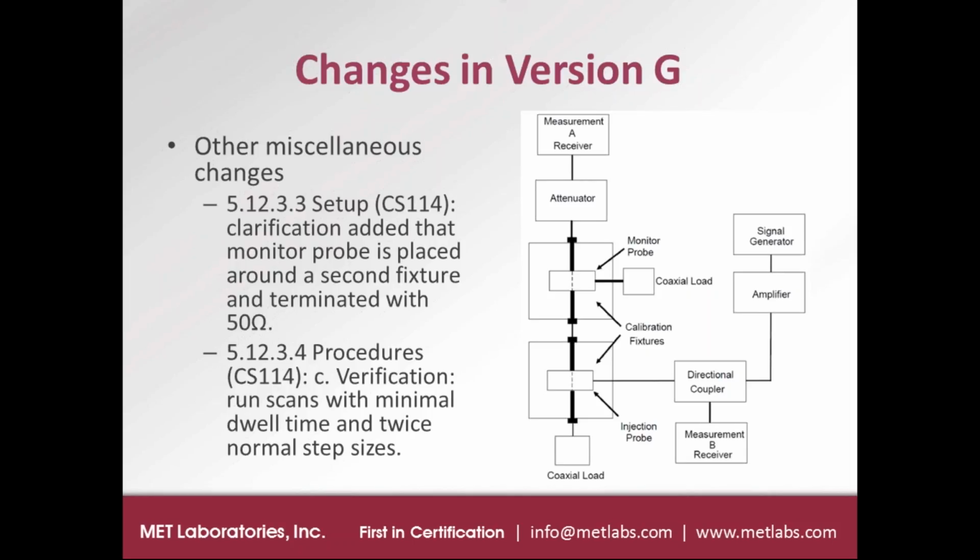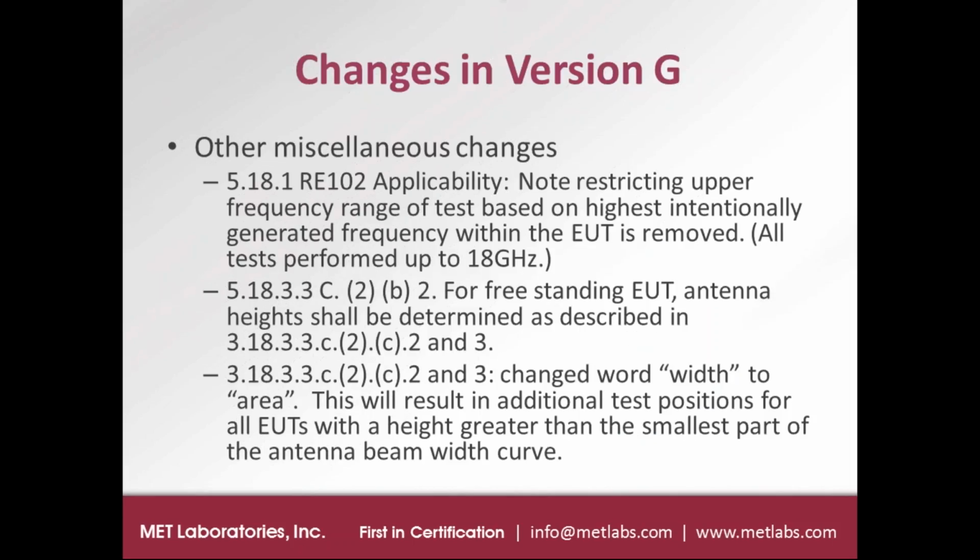Another change that was implemented is for CS114 calibration, whereas previously it was not specific regarding the use of an additional calibration fixture for the injection monitoring probe. Now it is specific to use separate calibration fixtures for those 2 probes. For RE102, there's a couple changes.